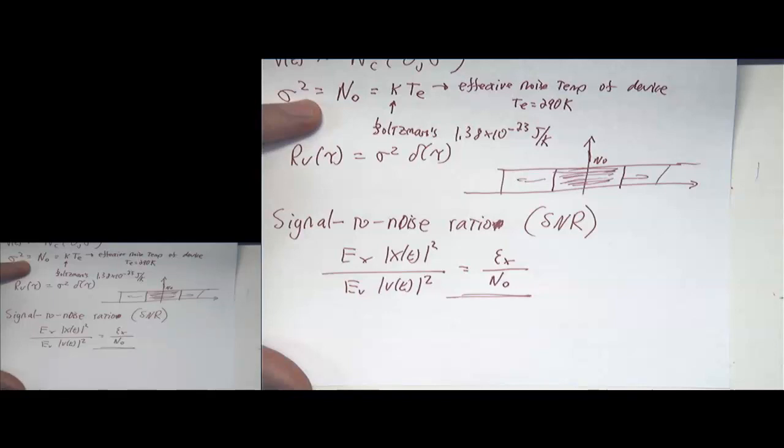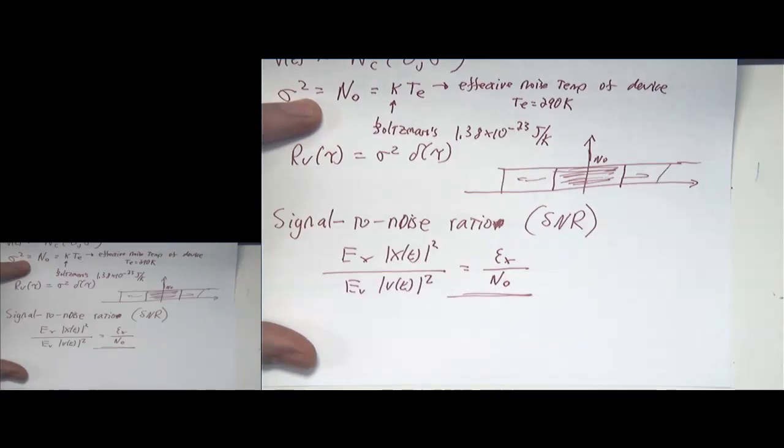So we can never detect the signal perfectly, at least unless we have enough coding and interleaving over a long period of time. Still, we can detect if it is less than 1. Yes, you can communicate at less than 1. We normally talk about SNR in dB, so 1 corresponds to 0 dB.